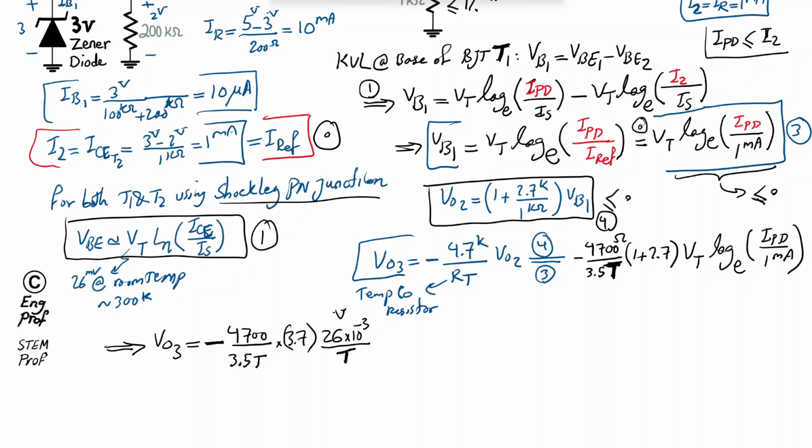The best thing to do is to divide it by, as I said, this is room temperature. If the temperature is more than room temperature, it will go up. So effectively I need to scale up by dividing by, let's say, 300 Kelvin, times the temperature. So that's the adjustment for the value of VT.